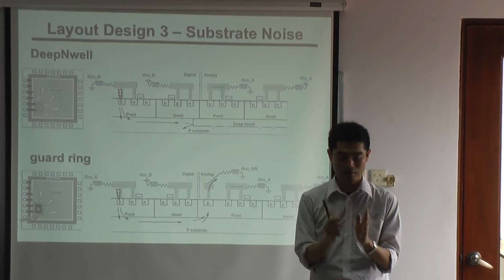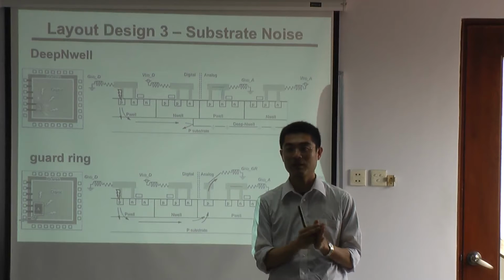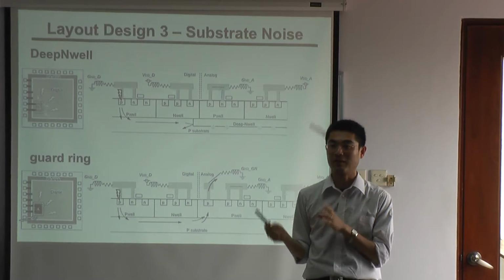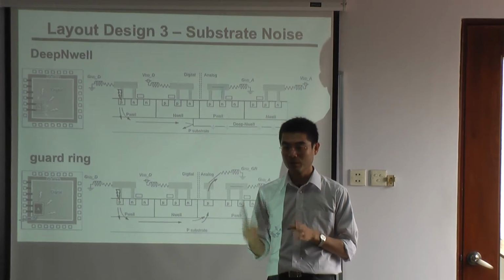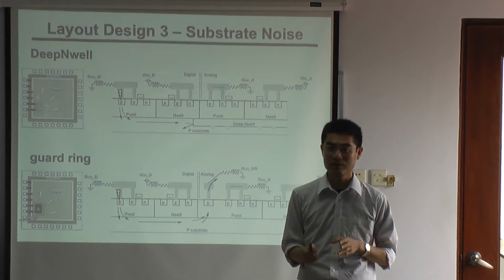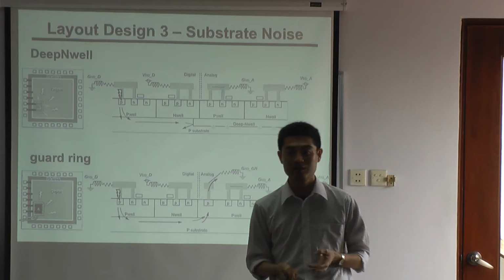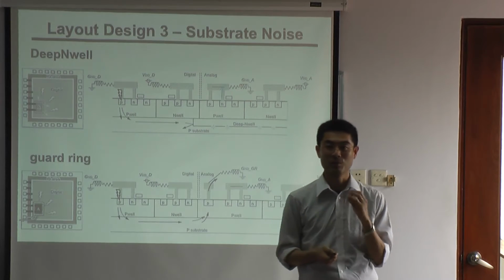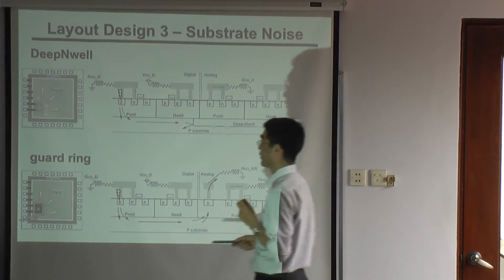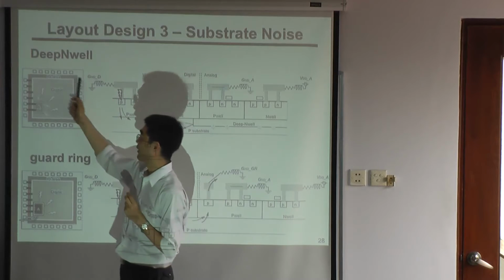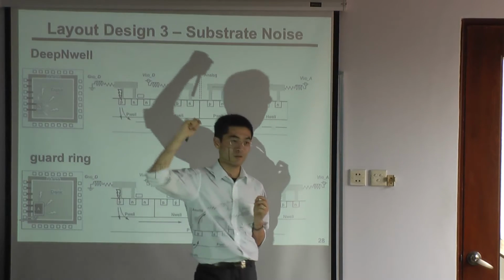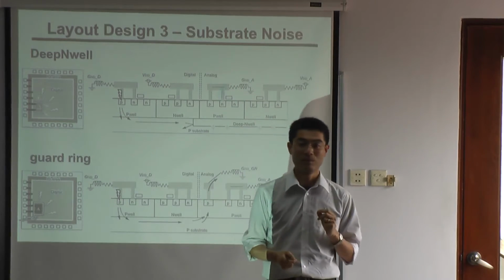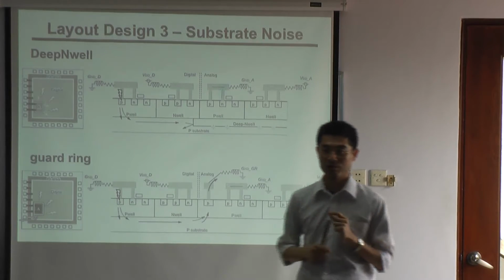The wires in the inverters have femtofarad capacitance, and the capacitance on the pad is picofarad. And picofarad at megahertz switching means a large amount of current flows. That means a large amount of noise is generated. So a deep N-well around I/O is also good for preventing the substrate noise.